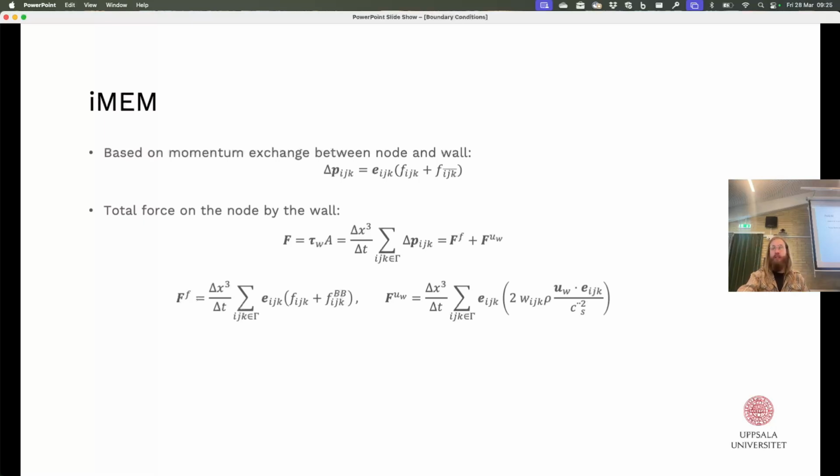I have the feeling there are also some simplifications doable of that algorithm, but it's just my feeling. Because it's a logarithmic profile you try to resolve, and the resolution maybe doesn't allow that. Some people argue that they adjust the wall model such that instead of having a linear eddy viscosity, they have a constant very close to the edge. It's kind of also giving rise to a kind of slip wall, which improves things. This is a Japanese paper from a precursor-like method.